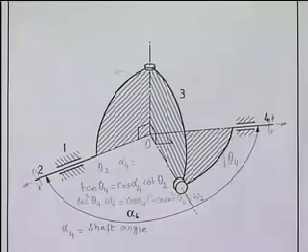However, we can use two such Hooke's joints in series to transmit a constant uniform angular velocity ratio. That is called compensating or self-compensating Hooke's joints, which are two Hooke's joints in series, which I will now show you the sketch.